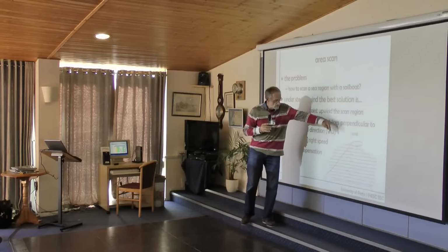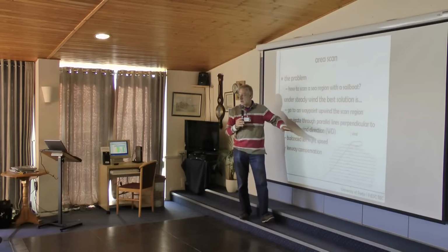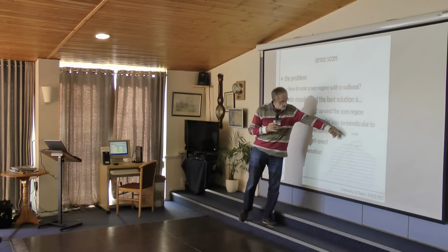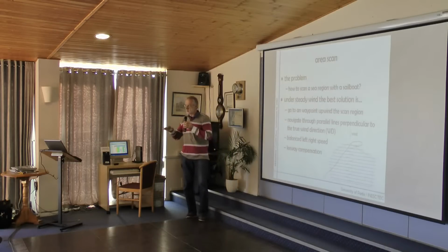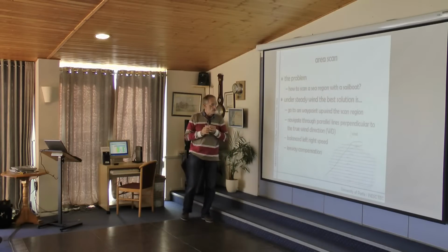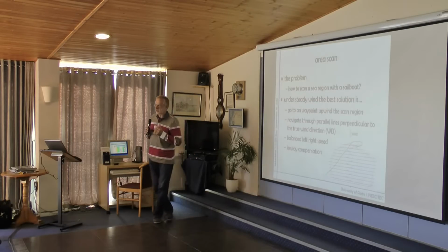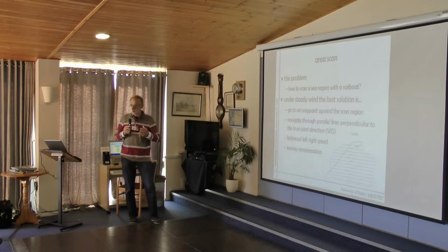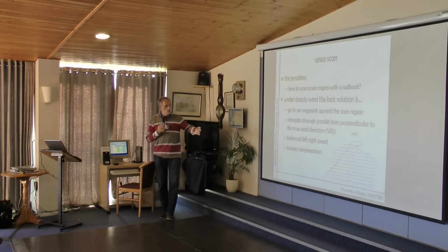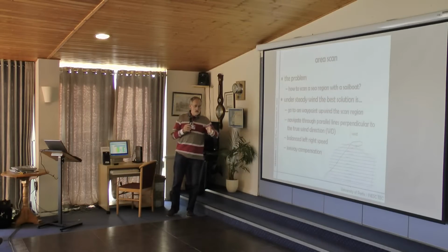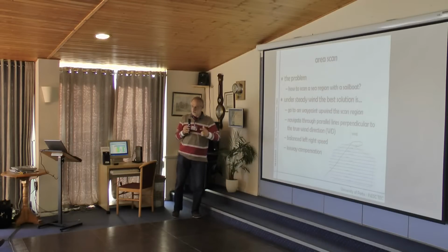If the wind comes from the north, from the top, to start the scan of this area with parallel lines, we should go to a point upwind and then navigate along lines that are perpendicular to the wind direction. And this is the best solution because it will give the best speed for the boat, usually for normal sailboats. In this situation, we will have similar speeds on the left to right and right to left legs.